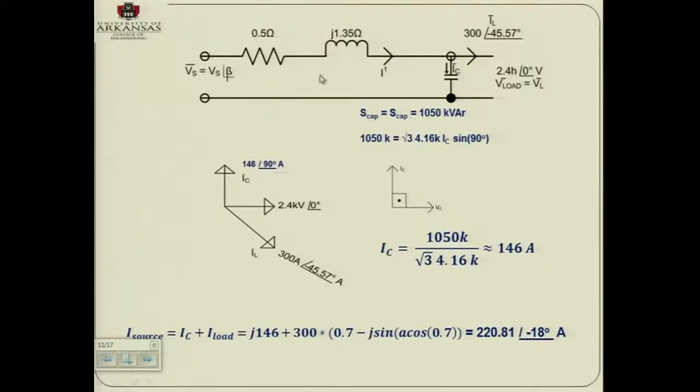But if this is a three-phase system, what is the assumption for this capacitor bank? How is the capacitor bank connected? Any three-phase piece of equipment can be connected in Y or delta, right? So what is the assumption that I'm making? That the value of C that I may have used is Y connected.